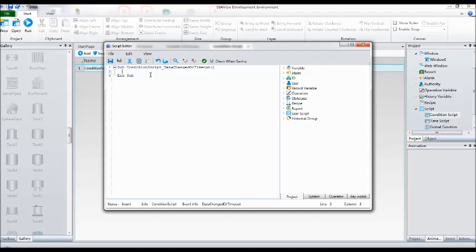So I'm going to type each and every condition here. In the beginning, the tank is completely empty, and the start button and stop button statuses are both false, or 0. If variable.start is true, what is our requirement? Tank filling should be started.